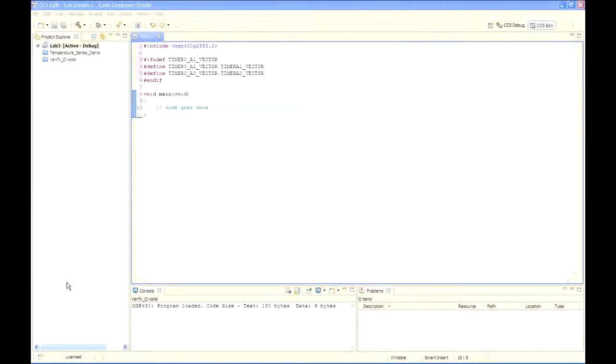This file contains all the register and bit definitions for the MSP430 device that we're using. You should also have the MSP430 G2XX User's Guide. That's the SLAU144. The latest version is the H version. That document was downloaded in Lab 1. This is the user's guide for the entire MSP430 value line family. Make sure you open that for viewing. You need to have both those files so you can understand everything that we're doing.